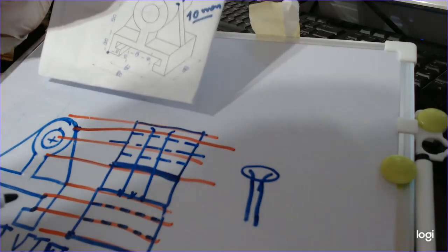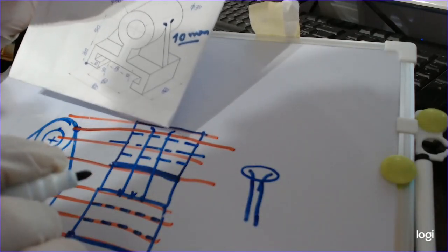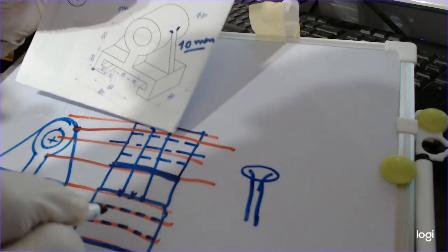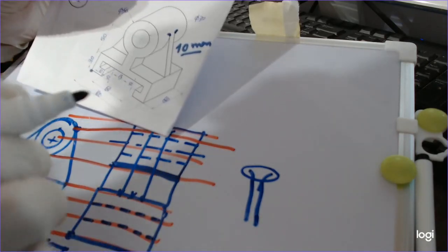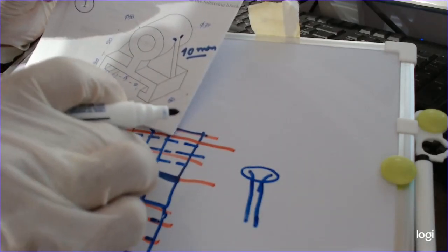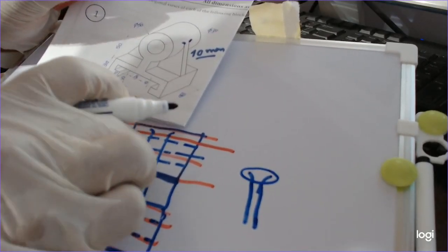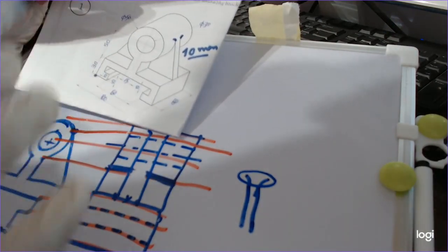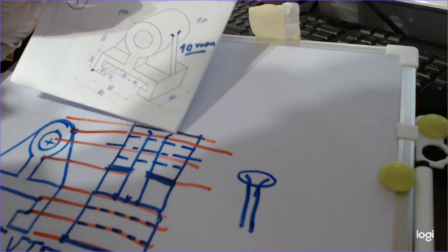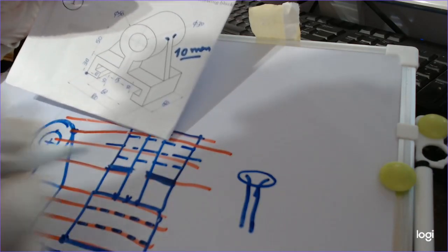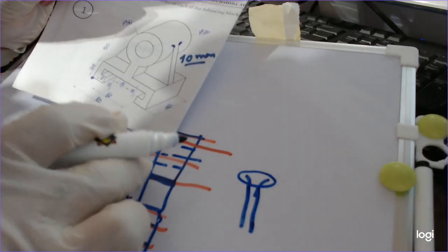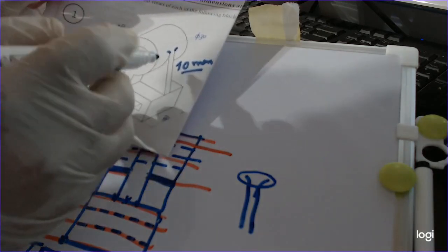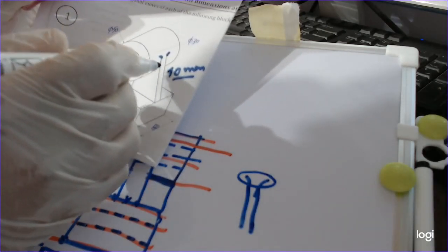Okay, so now we are not completing this view. We are missing something very important here. So we have a small mistake line. So some of you will say that we don't have this line, this portion of this line here, because it's like a fused or casted material. So the web is fused inside the cylinder. That means that we don't have something here. Okay, as written here or as drawing there, we don't have any lines here.